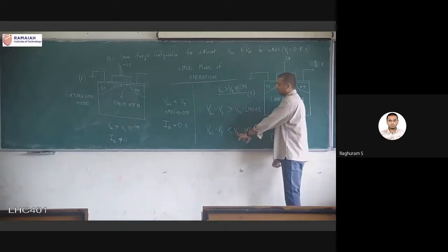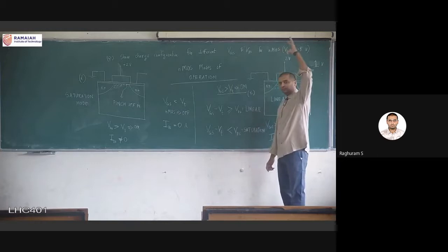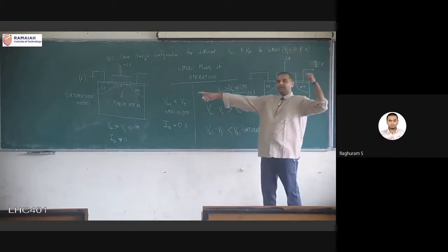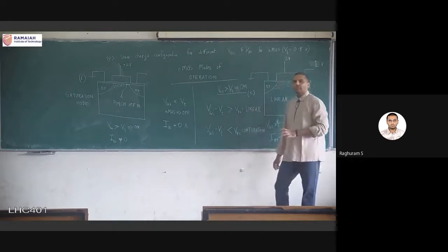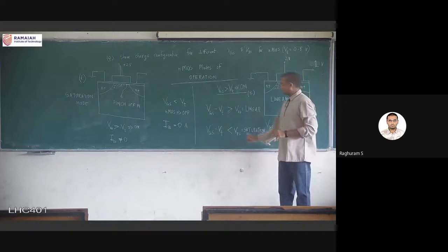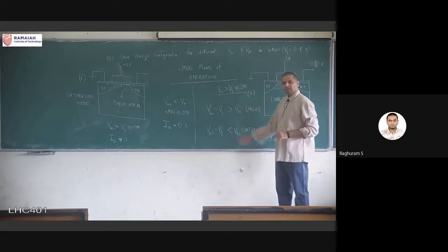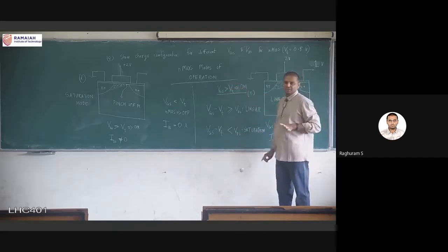The drain voltage is now higher, which means that pinch off has happened and the transistor is operating in saturation mode. So these are the two sub conditions within on. In both conditions, the transistor is definitely on, linear and saturation.